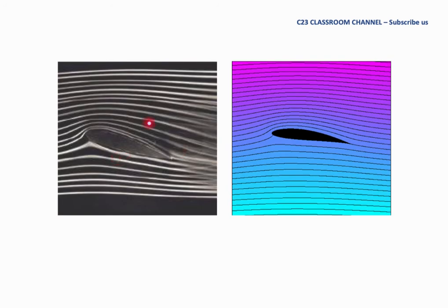And for example, this one is an experiment using a very simple object. We call it an aerofoil. So we put an aerofoil in the wind tunnel, and then we use a smoke generator, and we could have a lot of horizontal lines, which are the psi or the streamlines. In reality, in the wind tunnel, it shows like this. And then we will use these lines as our calibration or our reference.